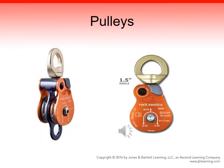Although a pulley is designed primarily to reduce rope friction, this capability makes it useful in a number of functions in the high-angle environment. Pulleys also can be used to change the direction of a running rope, position a rope more conveniently, reduce abrasion on a rope, and to develop a mechanical advantage in a hauling system. When life safety activities are involved, only all metal pulleys should be used. As with other auxiliary equipment, NFPA 1983 classifies pulleys as either T for technical or G for general use.